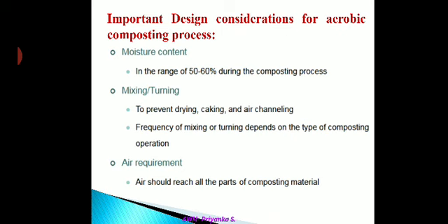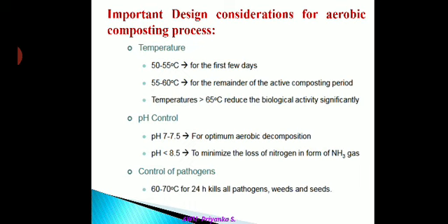Then the next is the temperature. The temperature should be 50 to 55 degrees centigrade for the first few days, then 55 to 60 degrees centigrade for the remainder of the active composting period. Then a temperature above 65 degrees reduces the biological activity significantly.